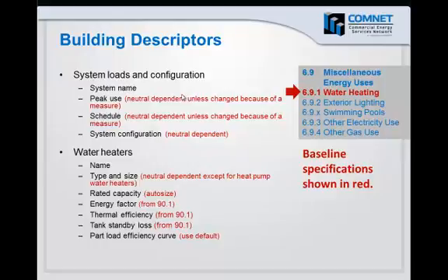The one exception to this is a heat pump. If the rated building has a heat pump, then you get credit for that, in that the baseline building assumes an electric resistance capacity, electric resistance type. The capacity is auto-sized, and the efficiencies, either energy factor if it's a small water heater that's covered by NAECA, or thermal efficiency if it's larger than that.